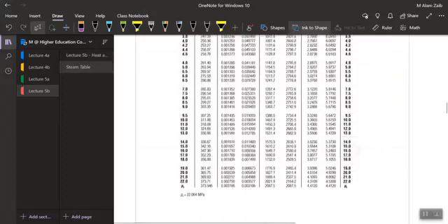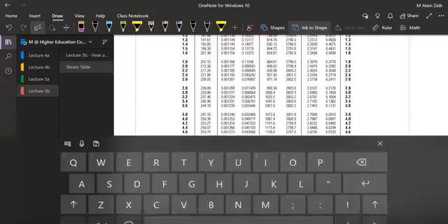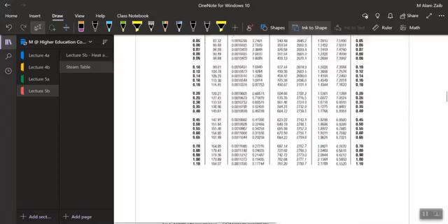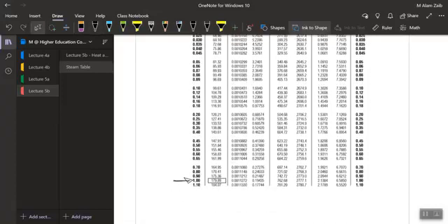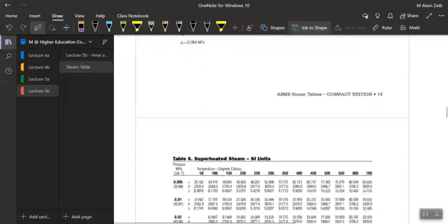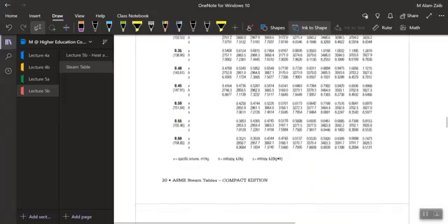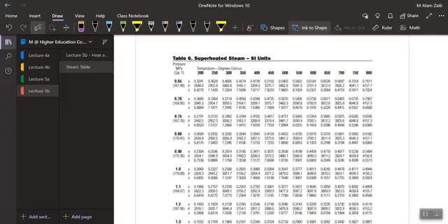So moving to the saturated steam table, 1 megapascal is somewhere here, and corresponding to 1 megapascal, the saturation temperature is 179.89. So as our given temperature of 500 degrees centigrade is higher, we would be in a superheated condition. So let's move to the superheated steam table and find 1 megapascal. I have got 1 megapascal somewhere here, at 500 degrees centigrade, and we are interested in the volume. At 1 megapascal and 500 degrees centigrade, I have got a volume of 0.3541.